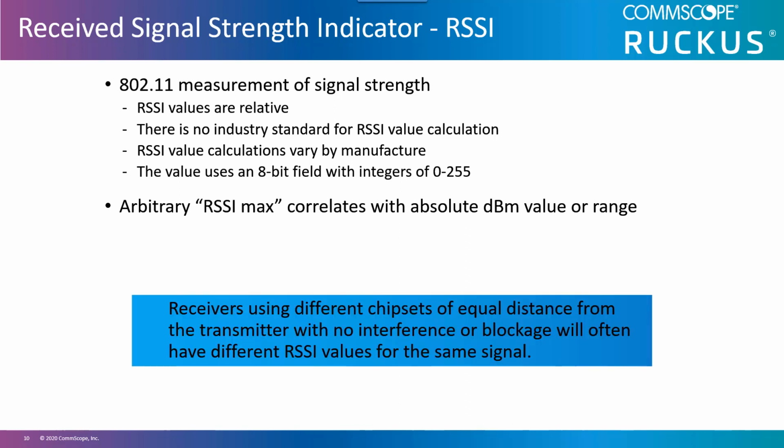The 802.11 standard states that RSSI is intended to be used in a relative manner and that absolute accuracy of the RSSI reading is not specified. It is usually measured during the reception of the 802.11 frame preamble. The RSSI will be seen as negative dBm values.